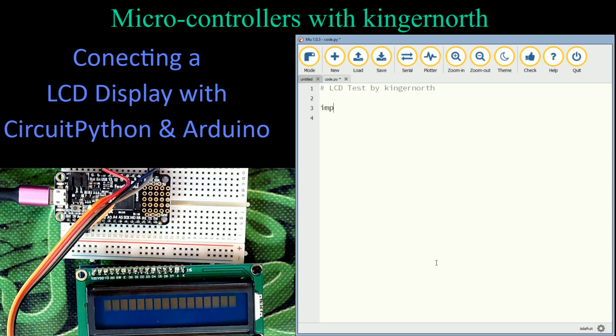So I'm going to write import time, because I want to put in some delays. I'm going to import board, because I need all the board connections, all the little wiring that's going to be needed. Import busio, because I'm going to be talking to inputs and outputs. And the last thing I'm going to do is an extra file that we haven't used up to this point.